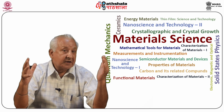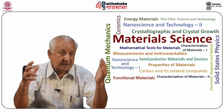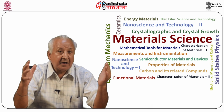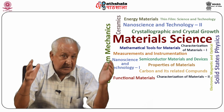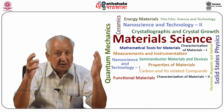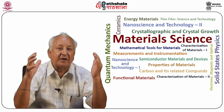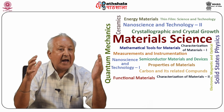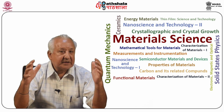The next major technique is growth from melt. There are subcategories in this category like the Czochralski crystal pulling technique, Verneuil flame fusion growth technique, Bridgman-Stockbarger growth technique, and crystal growth by zone melting. Other innovative techniques that fall under the subcategory of related growth techniques include plasma melting, liquid encapsulation pulling, skull melting, normal freezing, and directional freezing.